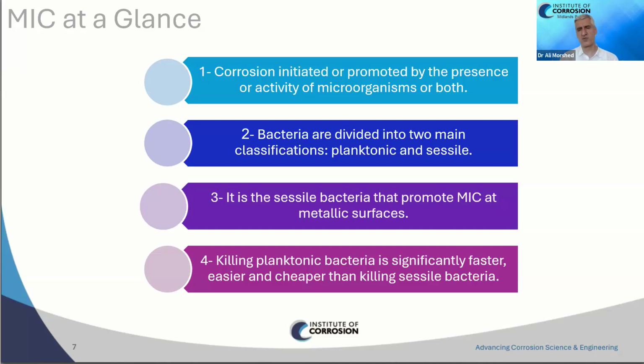Planktonic ones are the ones which are floating in the system. Sessile ones are the ones which are already stuck to the metal surface. It is the sessile bacteria that promote MIC at metallic surfaces. Killing planktonic bacteria is significantly faster, easier, and cheaper than killing sessile bacteria. Again, it's a very simple point.